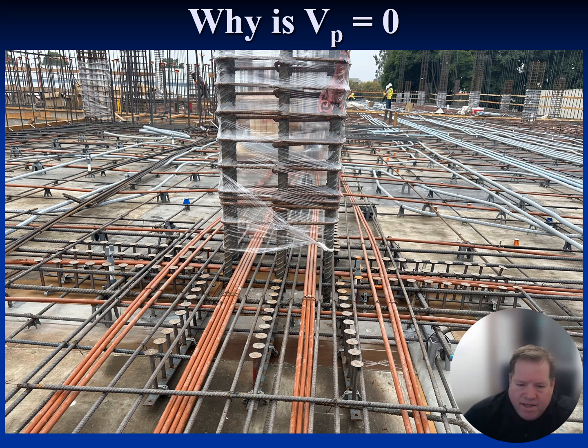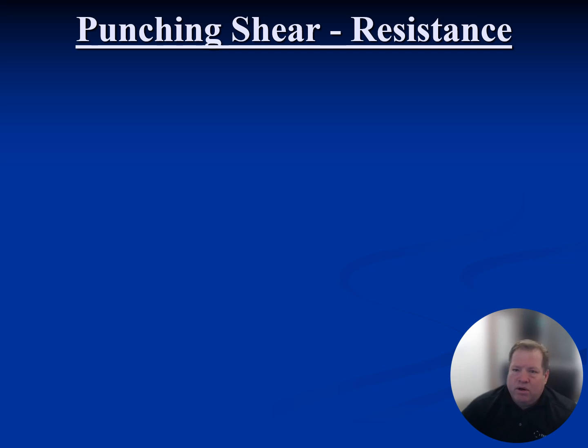These 3 strands and these 3 strands are now way outside the punching shear zone. So their point of inflection is going to push down into the slab, not into the column. Just because they push these out a little bit, which again doesn't change the flexural design, the balance load, the stresses, it has a huge impact on that V sub P term. So again, take it as zero, minimal benefits anyway, and you easily lose that benefit in the field. So that's why it's typically considered zero.